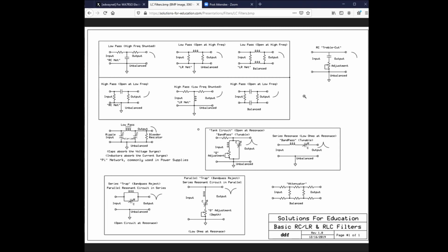Since it's dead center, that means the conduction at the center of a conductor is zero by comparison to anything further out. The square law principle comes into play, so that as you move from the center of the conductor out towards the skin, you have more and more conduction. And that's why at really high frequencies, they don't use solid wires, they use hollow tubing. And if you can go a step further and silver plate the tubing, that takes care of more of the skin effect. So you have a better conductor on the outside.